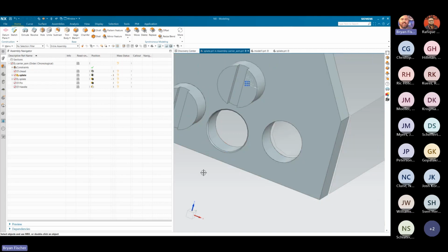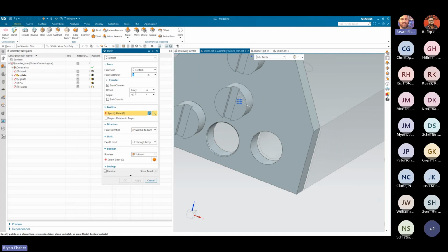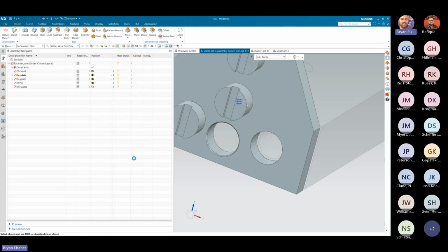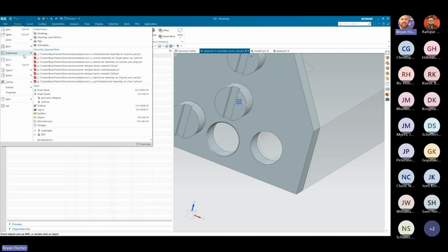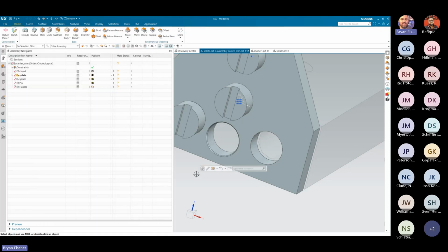Yes. So that's probably what's occurring: when you're in here, that start chamfer is left on, and you can turn that off just by selecting it. Now there may be other options within a customer default or a preference. I would have to go look. I'm sure there is within there. I would have to search for it though. But there are probably preferences that have that default as always off.